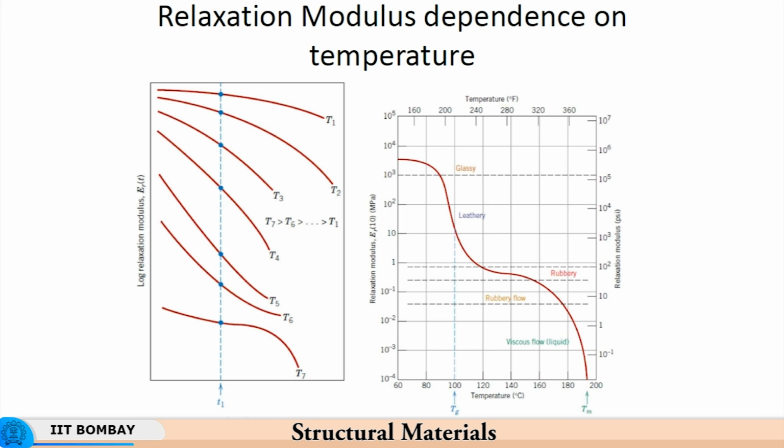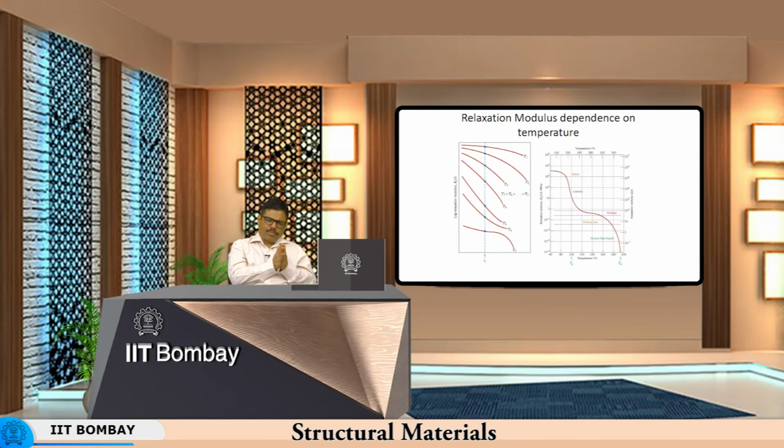Now, what is relaxation modulus? This relaxation modulus is typical to polymers. It doesn't exist in metals. It exists only in polymers, the reason being the two mechanisms which operate, namely the viscous mechanism and the solid one, the interatomic attraction between the two chains, or intermolecular attraction between the two chains. So both these parameters operate together.